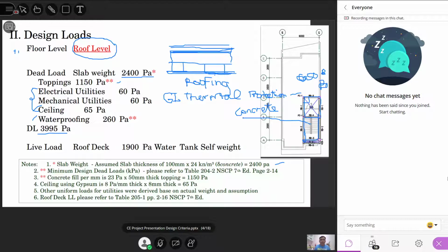So, yan ngayon, gagawan mo ngayon ng reaction, line of action, yung ating slab, to be able to transfer this load directly to your beam. Okay? So it depends on what type of slab that you are using, whether it is a one-way reaction or either it is a two-way reaction para ma-transfer mo yung load going to the member. Pagka na-transfer mo na yung load na yan going to the member, pupunta na tayo sa analysis. What type of analysis? Either moment distribution, frame analysis using Hilbert factor method, or using portal method. Okay, naintindihan nyo?